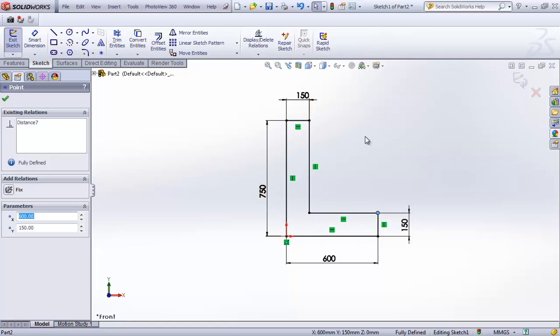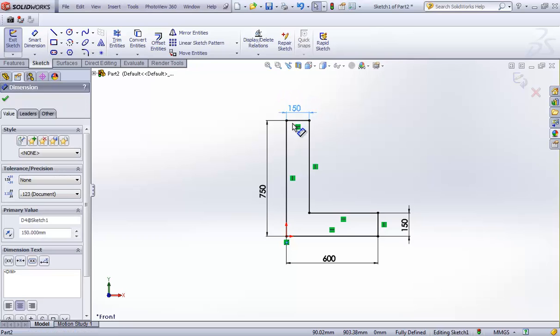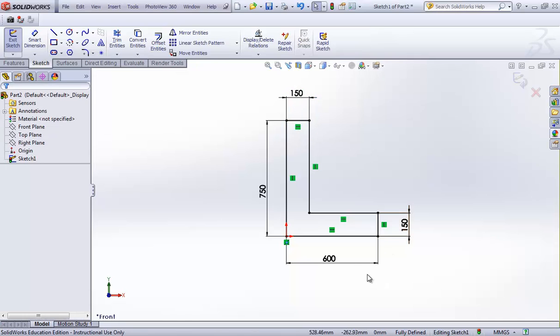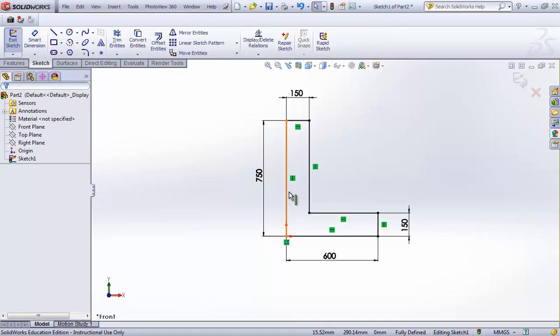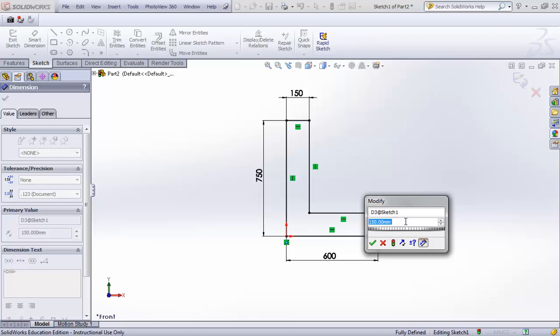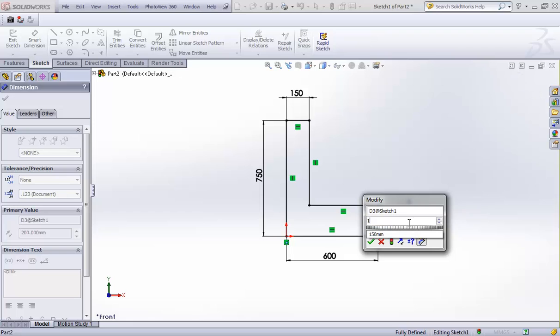It's a good sketch. It's a good idea for you guys to leave these dimensions behind. You need to make sure that you are not leaving these numbers out. We're going to try and stick to good modeling practice, good drawing practice, so that you can pass on your drawing to anyone and it is readable, it is editable, or you can come back to this drawing and without much trouble you can read and change the numbers. This is what designers and engineers do. They come back, change their mind every now and again, redesign. So I want to be able to see these numbers nice and clear, so I can double click on those numbers and change them to a different value for whatsoever reason.